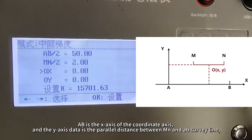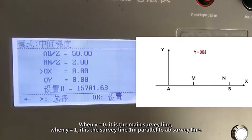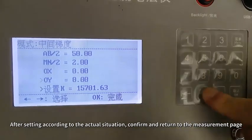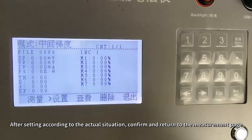AB is the x-axis of the coordinate axis, and the y-axis data is the parallel distance between MN and AB survey line. When y equals 0, it is the main survey line. When y equals 1, it is the survey line 1m parallel to AB survey line. After setting according to the actual situation, confirm and return to the measurement page.